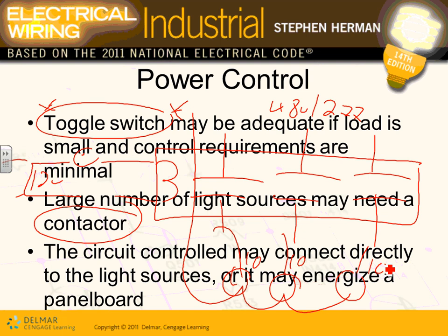That's kind of the high end. When we drive around the cities here, you see all these parking lots. Good morning. And all these lights, major parking lots, guys, are controlled by lighting contactors. It's one step above timers. The timers also have a contactor, and what drives these contactors is a timer, an atomic clock, or a computer. You can make a computer drive these contactors.